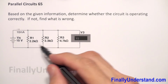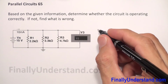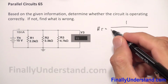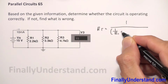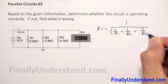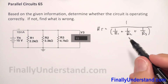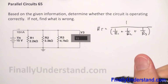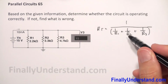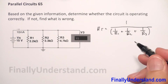Because I have more than 2 resistors, I'm going to use the following formula. R total is equal 1 over 1 over R1 plus 1 over R2 plus 1 over R3. Keep in mind we use this formula when we have more than 2 resistors. Mostly, because we can also use this formula for 2 resistors, but we used to use product over the sum for 2 resistors.